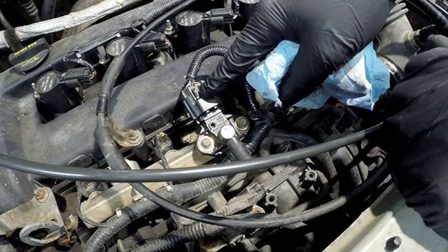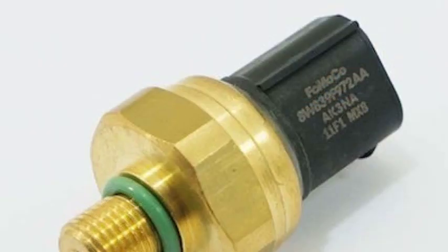The repair for the P0191 code will depend on the underlying cause of the problem. If the problem is caused by a faulty sensor, then you will need to replace the sensor. If the problem is caused by a clogged fuel filter, then you will need to replace the fuel filter. If the problem is caused by a fuel pump problem, then you will need to repair or replace the fuel pump. If the problem is caused by a fuel injector problem, then you will need to clean or replace the fuel injectors. If the problem is caused by an electrical problem, then you will need to repair the wiring or replace the ECU. The P0191 fault code can be caused by a variety of problems.